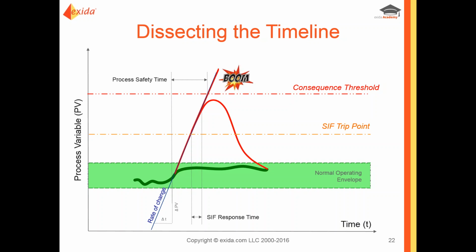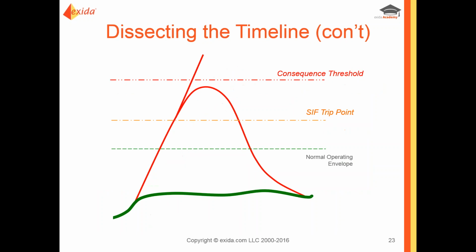We know that our SIF response time is somewhere in the middle, starting at that SIF trip point and ending at the point where the SIF is finished acting and it's started to change what's happening in the process variable and bring the process back to a safe state. Looking at this on just a little bit larger graphic, we'll put those two times back up there.